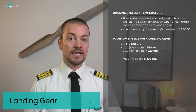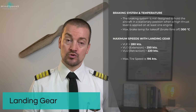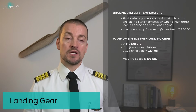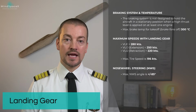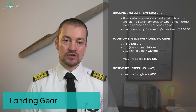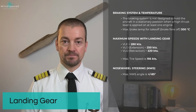Maximum speeds for the landing gear: VLE, landing gear extended, was 280 knots. VLO for extension was 250. VLO for retraction was 220. And maximum tire speed was 195. The nose wheel steering has a maximum steering angle of plus or minus 85 degrees on either side. This, of course, is a limitation that will not be applicable if the aircraft is being towed on the ground.